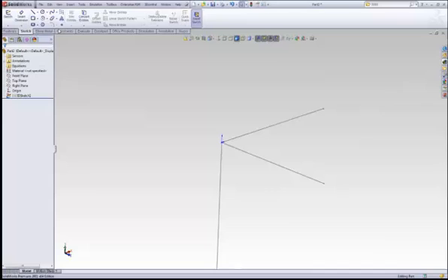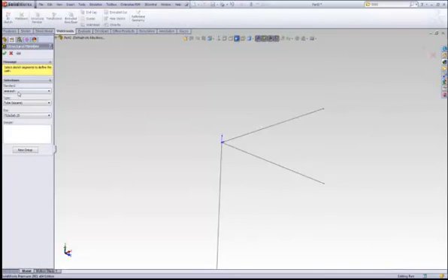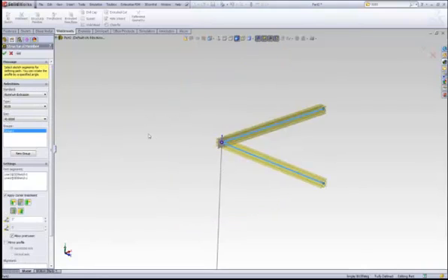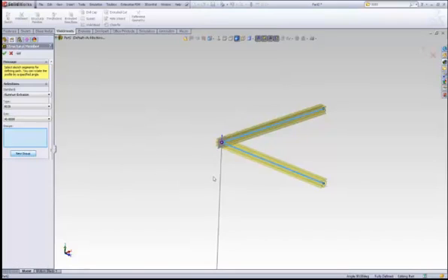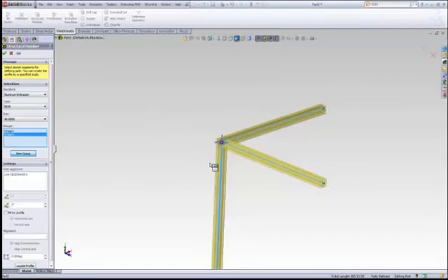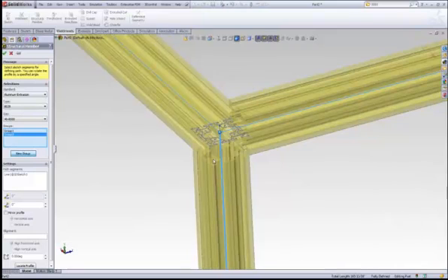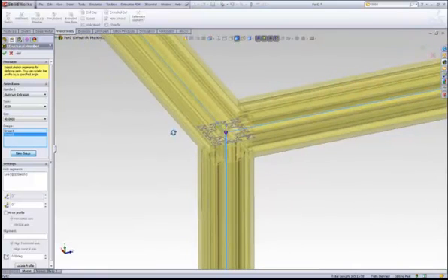So now when I add a new structural member using my new folder in size, we can choose those. I'll use a new group for this one right here since it's not parallel. By the way, there's additional trim options that are available too for these corners.